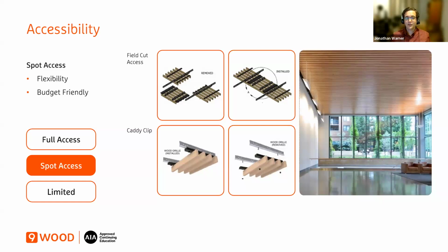The real benefit of this is it takes an existing module panel, whatever it is, so 1 foot by 6 foot or 1 foot by 8 foot or 1 foot by 10 foot, and it turns it into an access panel. And with these little clips, it goes right into the standard 15/16 heavy duty grid. And so it works out great, blends in, you can't see it.